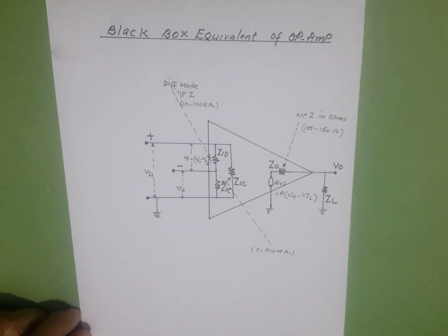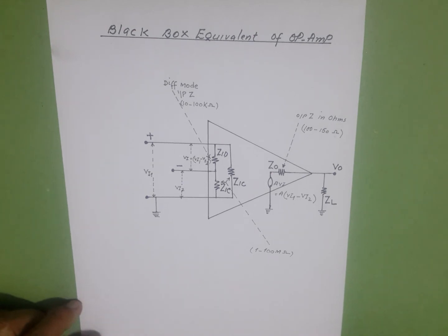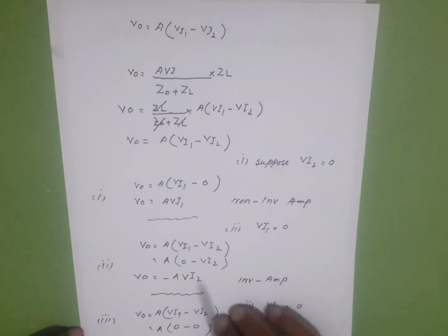There is a small amount of voltage available in the output due to unequal behavior of transistors in the operational amplifier. They have unmatched characteristics and are not perfectly balanced. As such, they produce a small amount of voltage in the output despite both inputs being 0. This small voltage is called the error voltage, which is not desirable.